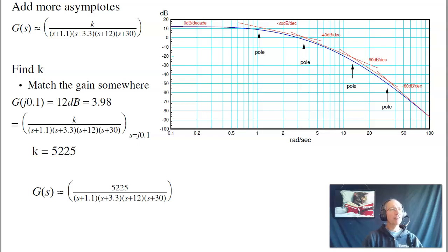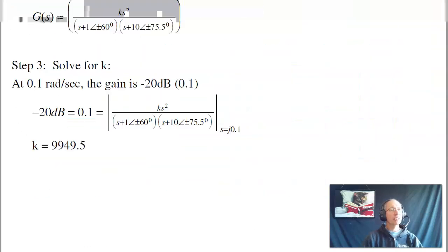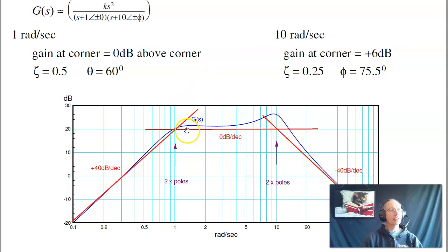The one caveat, a mistake I see a lot of students making, is on this graph, don't overdo it with the slopes. Like some people say this is flat, then plus 20 dB per decade, flat, minus 40, or minus 60, then minus 40. That doesn't actually work. If you have a hump like this, that's a resonance. I just have a single complex conjugate pair right here, and the angle tells the damping ratio, or the angle tells you the resonance.